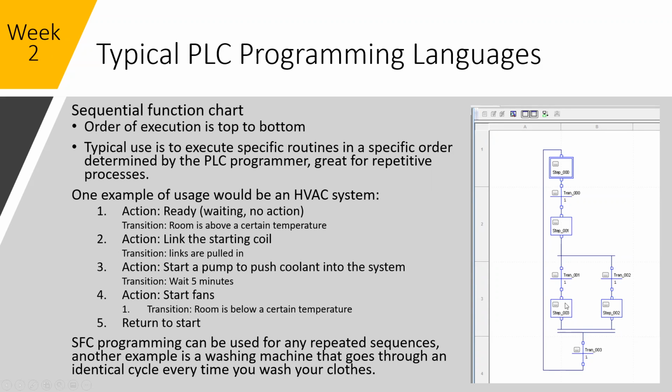So if something fails in here, so let's say inside step 4, it started this fan, well, you're going to have another routine outside of this. It's going to be looking at the fan. And if there's a fault for the fan, or this step in here could be a custom function that is called fan controller, you would have to kind of encapsulate the fault inside of that function block.